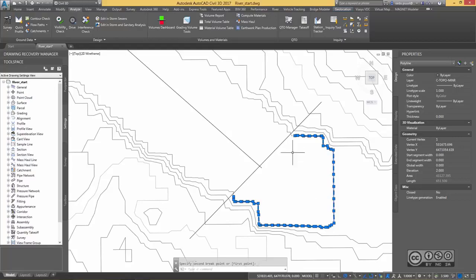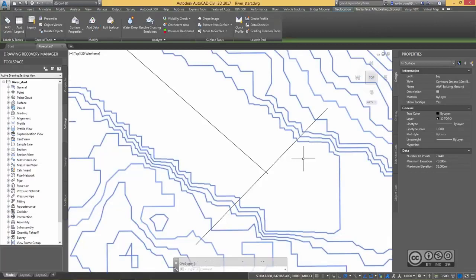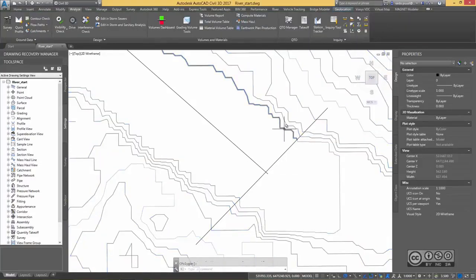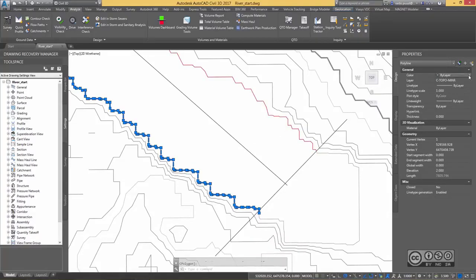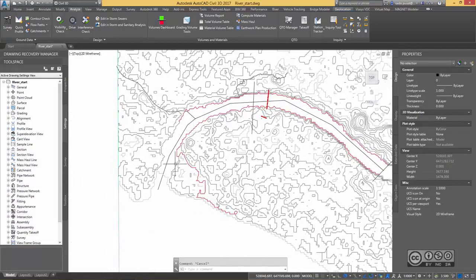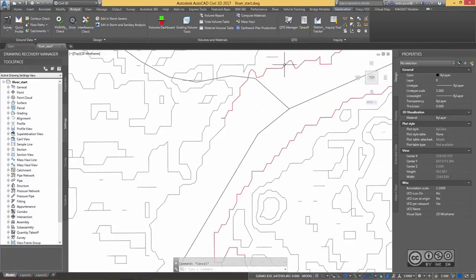And if I don't need it, I will delete this line. I still have my surface valid, so nothing to worry about if you delete that line. Maybe it's easier, if you are so-called digitizing riverbank lines, that you use some other color value. For example, I use red here, maybe red in here. And now it's easier for me to see where I should continue my line or connect to another line so that I can get one long polyline from start to finish.